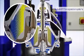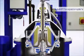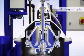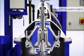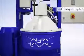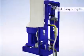The layers form because of the specific gravities of the materials in the mixture. If the oil, water, and sediments are placed in a container that is revolving rapidly around a vertical axis, the effect of gravity is negligible. Since centrifugal force acts at right angles to the axis of rotation of the container, the sediment with its greater specific gravity assumes the outermost position, forming a layer on the inner surface of the container. Water, being heavier than oil, forms an intermediate layer between the layer of sediment and the oil, which forms the innermost layer. The separated water and impurities then are discharged.